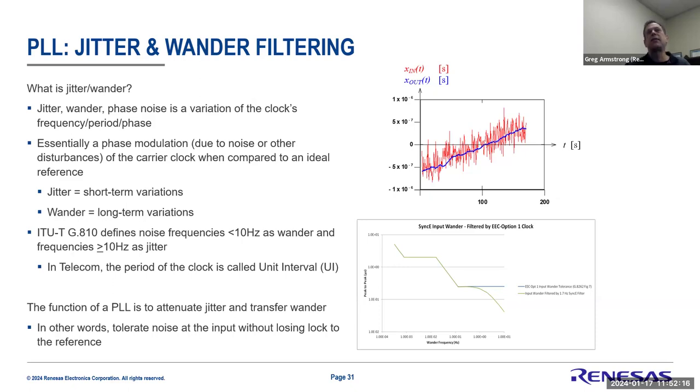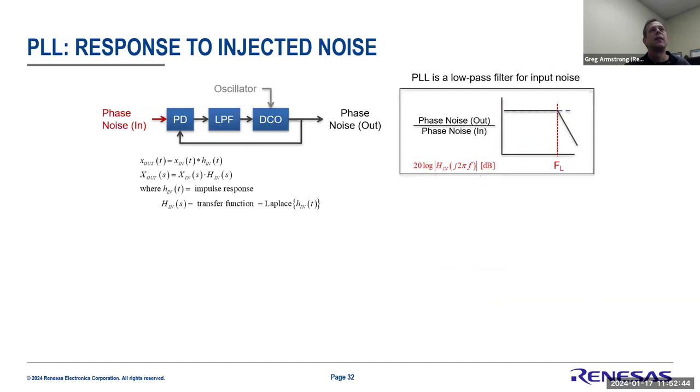And when you look at frequency, a lot of times you're typically looking at just maintaining microseconds of phase traceability to that clock, right? Because a lot of times components allowed the ability to do jitter buffers and control that. So that's why in the early days, what a phase lock loop really did is just allow you to follow that drift over time, but attenuate some of the high frequency noise.